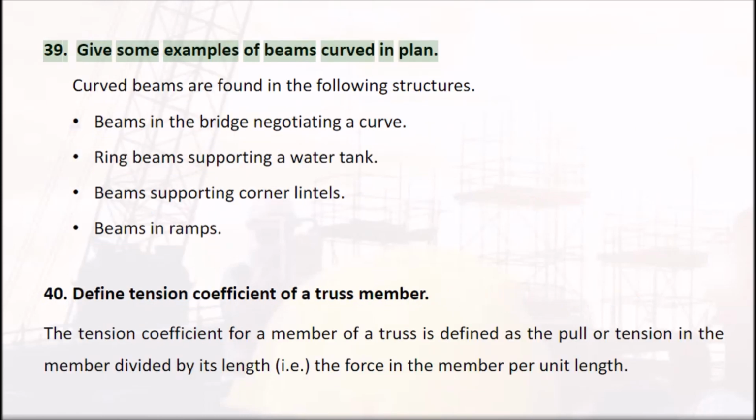Give some examples of beams curved in plan. Curved beams are found in the following structures. Beams in a bridge negotiating a curve. Ring beams supporting a water tank. Beams supporting corner lintels.